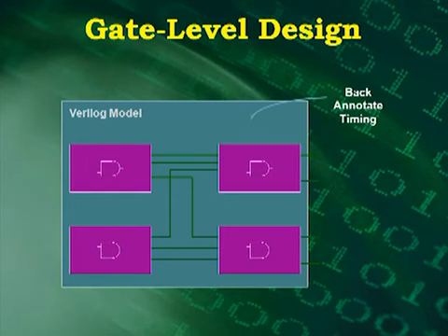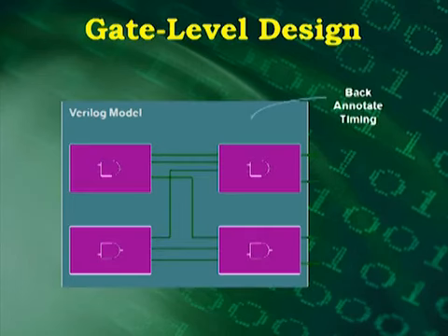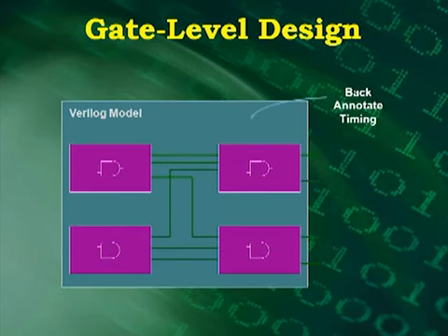You can also, after you've gotten your design down to the final gate level, or assuming you're going to make an FPGA or an ASIC or something like that, Verilog is good for doing what we call back annotating. You can back annotate timing. That is, you can put timing information into the model that is very close to what the real device is going to have. And a lot of vendors, even when you're doing FPGAs, you can back annotate this timing information into the model, and then you can simulate it, and you can see what the physical delays are going to look like coming out of this.